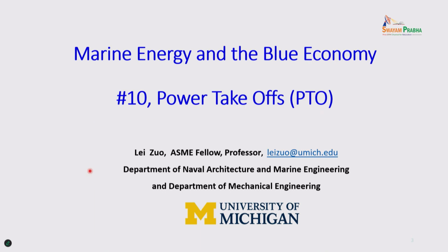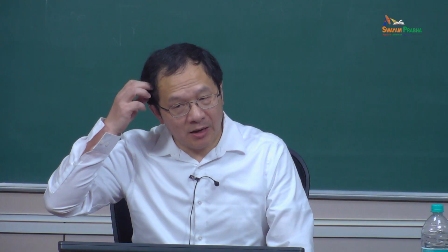We also learned about the point absorber. We talked about the linear electromagnetic transducer and motion transmission plus some generator. We also learned about piezoelectric and triboelectric energy converters for small-scale energy. For us, usually we use larger scale, therefore electromagnetic is used. A direct-drive electromagnetic transducer like that is usually very, very heavy, so most likely we are going to use motion transmission.